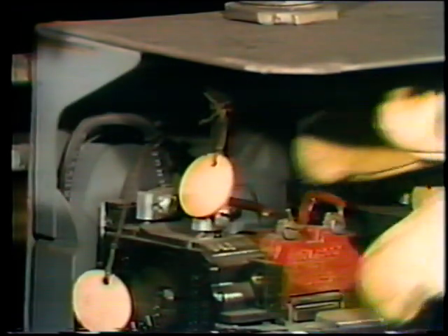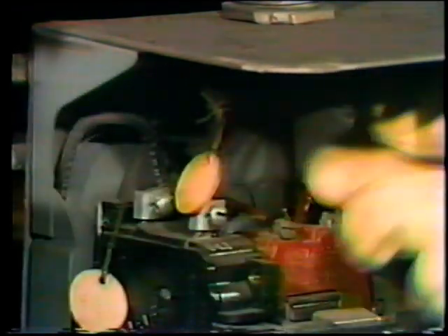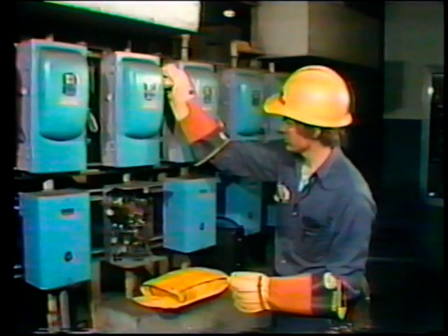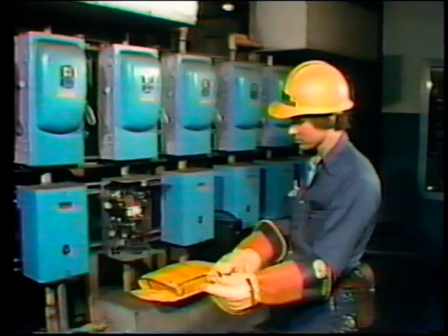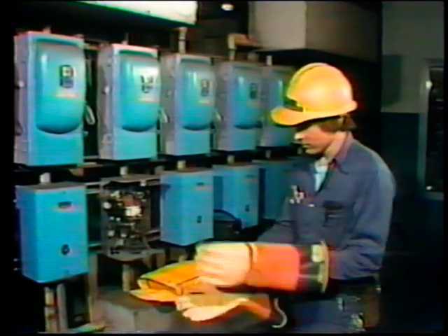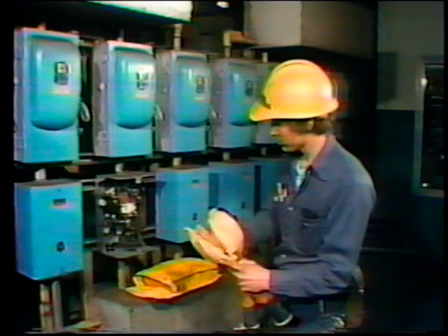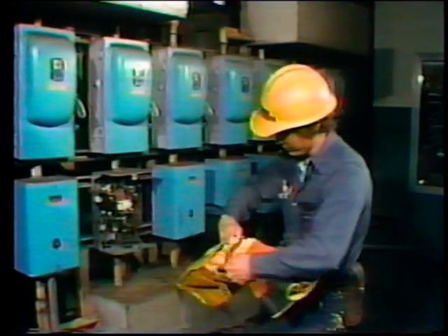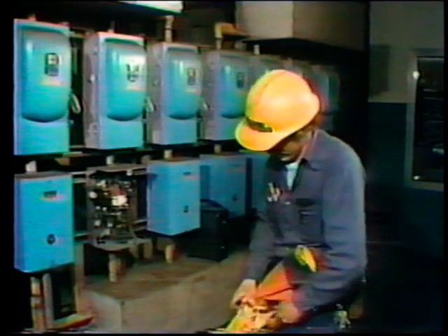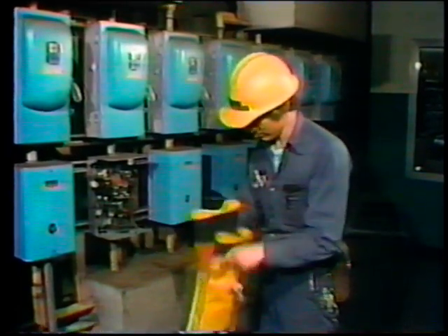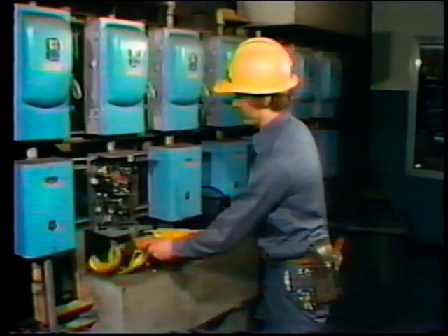After a thorough examination, he discovers a broken wire on the operating coil. Upon discovering the broken wire, the electrician immediately pulls the power supply breaker down to open the circuit from the power supply to the controller, so that the broken wire will not cause a short or a ground to occur in the controller. It seems likely that the broken wire has caused the controller malfunction.